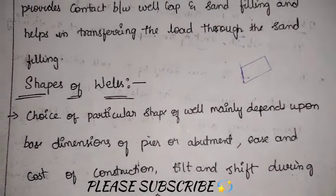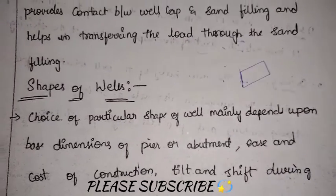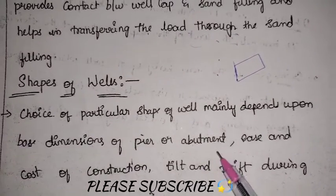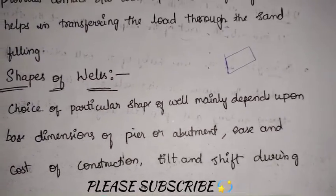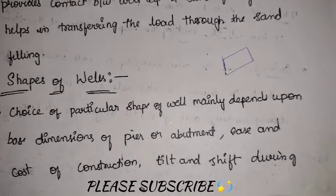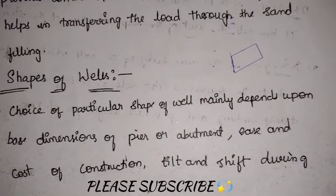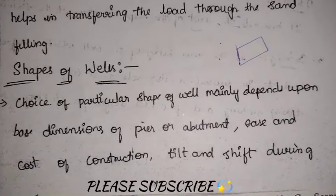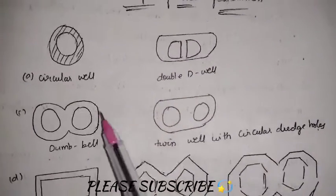So the shape of the well is selected such that it satisfies all the basic requirements. It depends upon the base dimensions of the pier or abutment, the ease and cost of construction of this well, and tilt and shift. Whatever forces are about to occur, it should be able to resist those forces. It should be able to resist the tilt and shift.